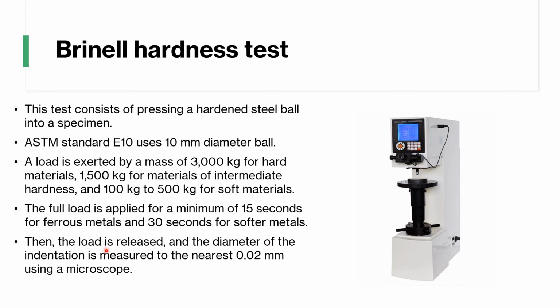And then you release the load, and the diameter of the indentation is measured to the nearest 0.02 millimeter using a microscope, okay? So that's how. Here is your microscope right there. You can't see it in the display.